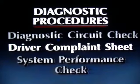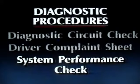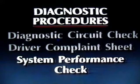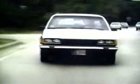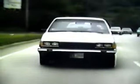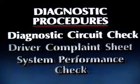Step 2, the driver complaint sheet, is used when Step 1 fails to reveal any trouble codes or when no repair is called for after following the chart. Like Step 1, the driver complaint sheet has a chart to follow so repairs can be made. Step 3, the system performance check, is done after any repair is made or when no problem can be identified from working Steps 1 and 2. If no problem is found after a system performance check, then you can usually conclude that the car is in proper working order. Now that you understand what each phase entails, let's examine them more closely.